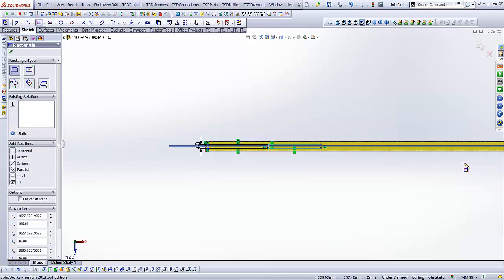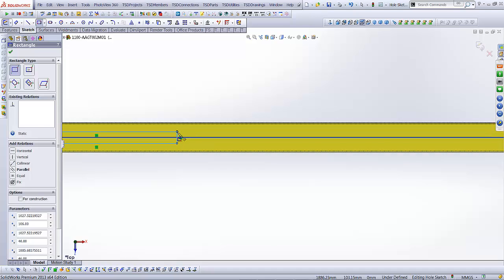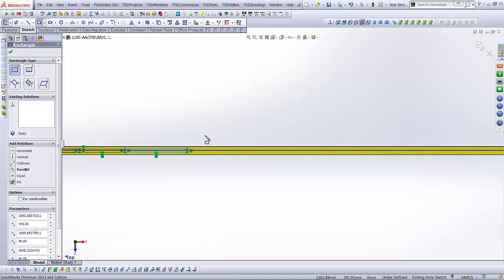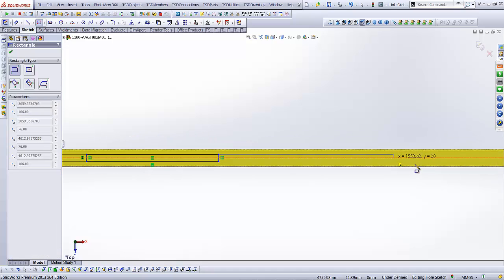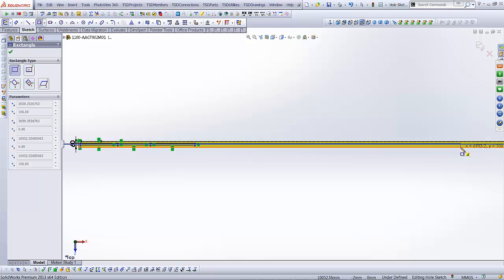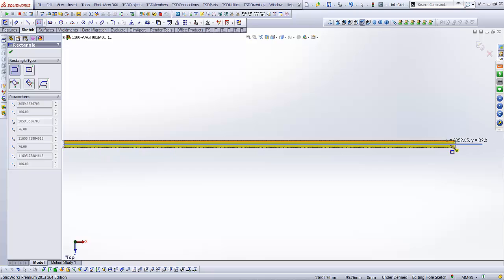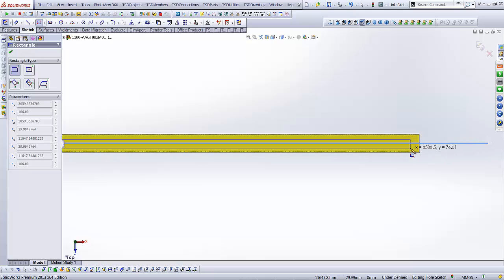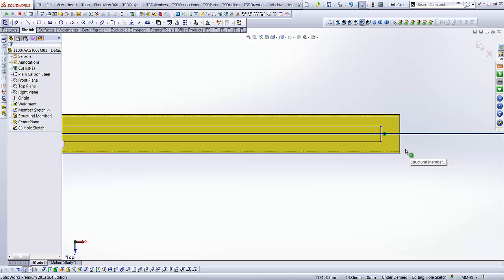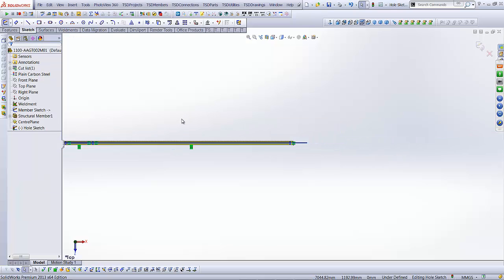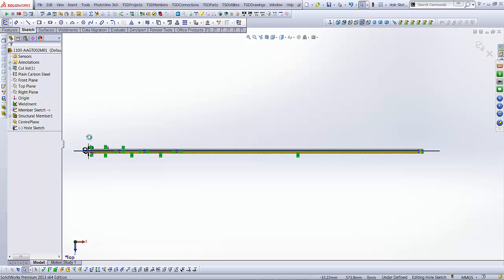So that's in. Now that last vertical line is where a column line is. This is another bridging holes, and you'll find that I'm way off as far as the scales go, but that's okay because we're going to lock these into position in the girt when the time comes. So we've got column, bridging, and we need to come up to here, and you'll see that it snaps on, and we're still maintaining the 60 centers. Now this end we don't trim. We don't know what the dimension is, but we're going to lock it on, but we'll keep it floating at the moment.